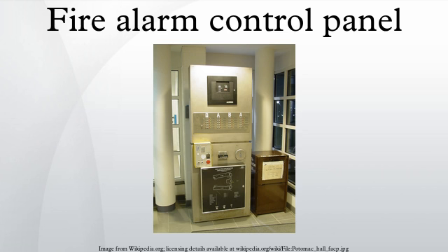Signal silence, also known as alarm silence, or audible silence. Depending on the configuration of the alarm system, this function will either silence the system's notification appliances completely, or will silence only the audible alarm, while strobe lights continue to flash. Audible silence allows for easier communication amongst emergency responders while responding to an alarm. This can also be used during construction as a means of a preliminary test, before the final full test. This is very effective.